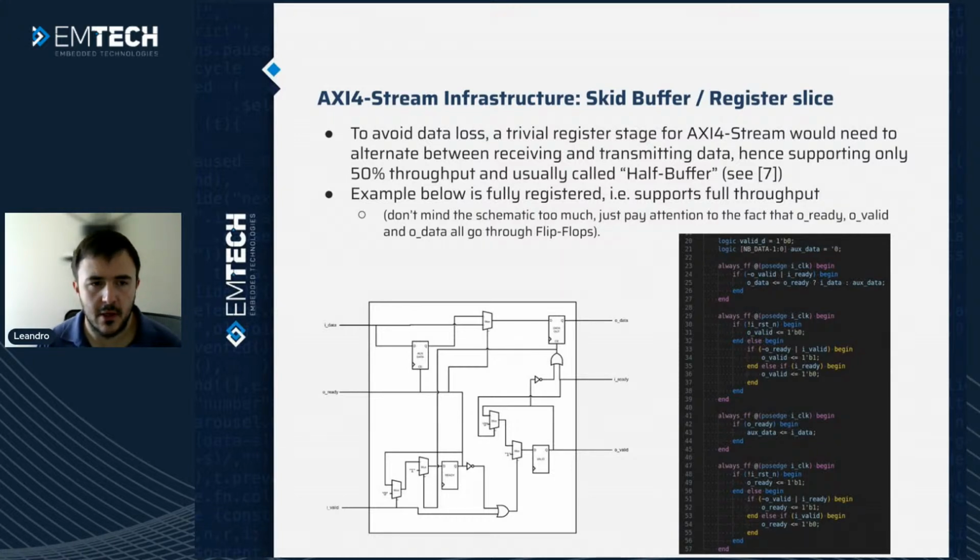The code example on the right is exactly the same design, and the idea is the same. So you can see that the data, the valid, and the ready, they're all implemented inside an always flip-flop block of SystemVerilog. So yeah, they have to be synthesized into flip-flop registers.